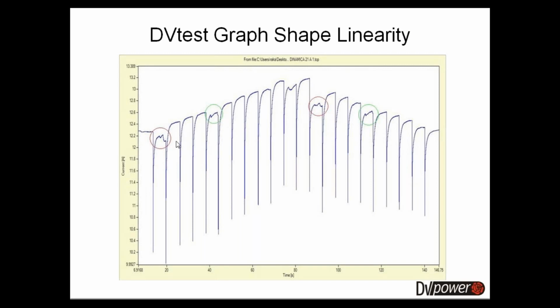And these parts correspond to specific points in the tap changer operation where the tap changer uses the same contacts twice. So here it happens on position 2, and here it happens again on the second position past the neutral point. And again you have 2 symmetrical places where the problem happens, marked in green. So this tells you immediately, without the need for any further analysis, that a contact problem is visible on 2 specific points in the tap changer mechanism.